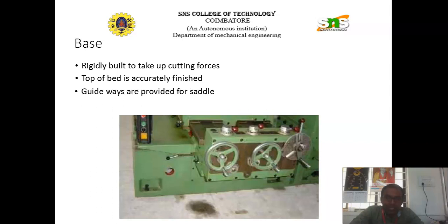The top of the bed is accurately finished in order to accommodate the other parts of the slotting machine, and it also has the guideways provided for the saddle. Guideways are perpendicular to the column face.